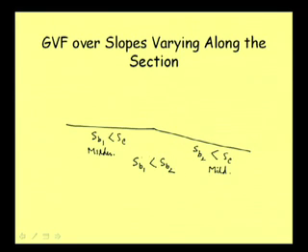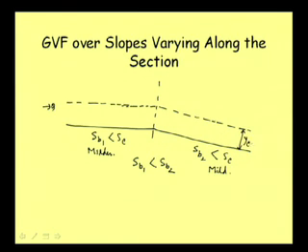Okay. Again, so far as critical depth is concerned, this will be the same. For a given discharge, this will be the same. So, if Q is the discharge flowing, we can calculate the critical depth, and let me draw a line here, which is indicating the boundary of this channel and that channel. So critical depth is fixed, critical depth is constant, it is not changing. Okay. Well, so that is our critical depth YC.